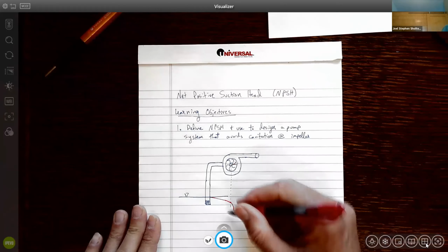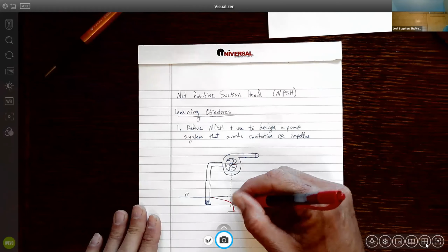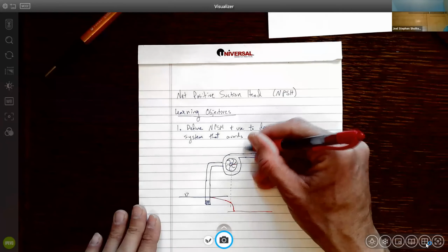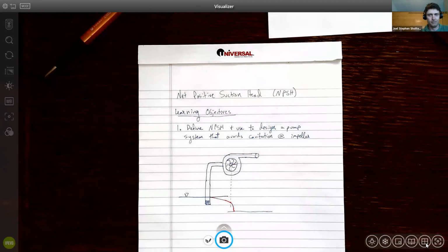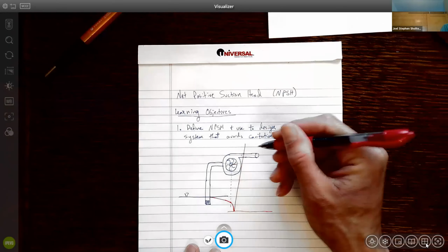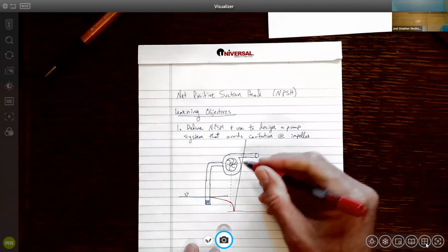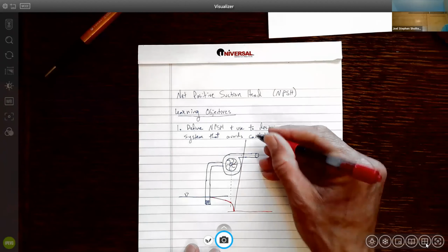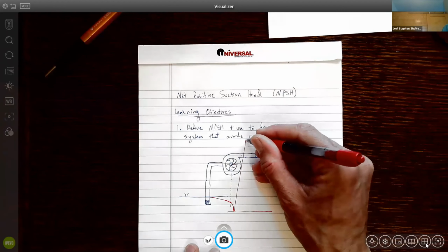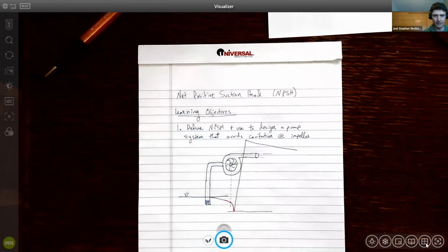Now, once we get off of that impeller and we're back in the pipe, that's where the pump head is imparted and the pressure suddenly increases again. Here the flow is super fast, maybe 30 meters a second, because that impeller is spinning so rapidly. But now we get back to our normal discharge, our normal flow rate, and that's when the pressure skyrockets. So that's the head that the pump gives to the flow once we get off that impeller face. And then we're in our pipe system, and we start to lose energy due to friction.